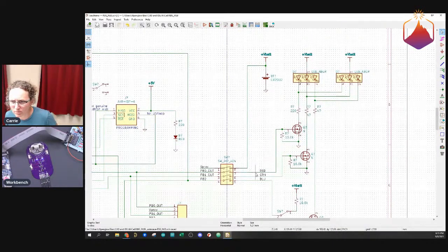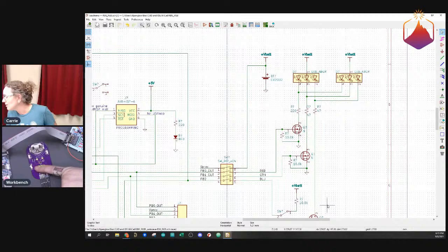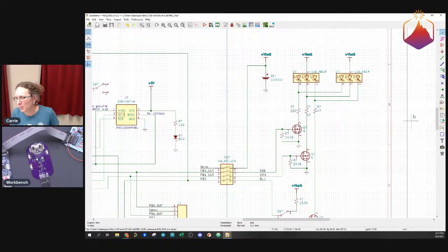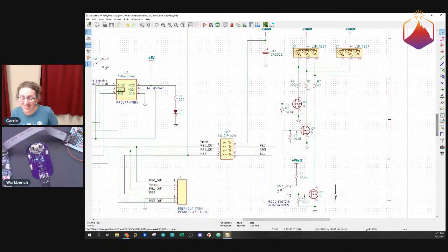And because this one you added after the fact. Yeah, that one I added after the fact. The programming switch I added after the fact, yes. Because I didn't realize at the time that I laid out this board that I would need the programming switch, and then I realized I needed it to isolate the chip from the rest of the circuitry while I was programming it. Because, as I said, I laid that board out in a weekend in a fit of angst, and so I didn't realize that it could only be programmed at 5 volts, and then I would need to switch that. And, anyway,